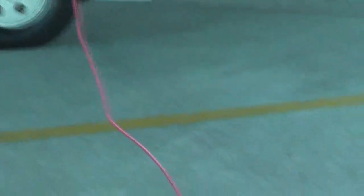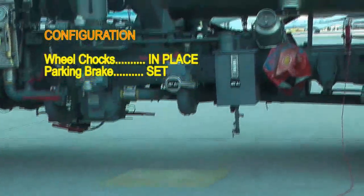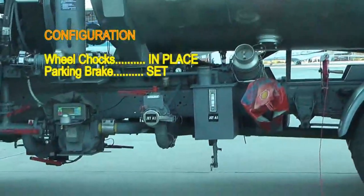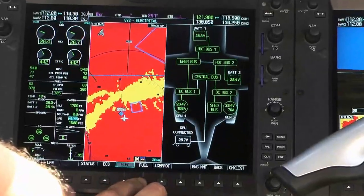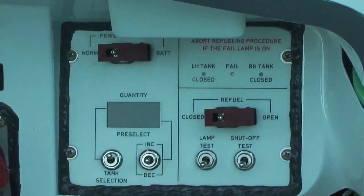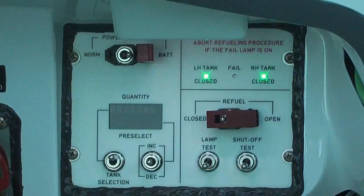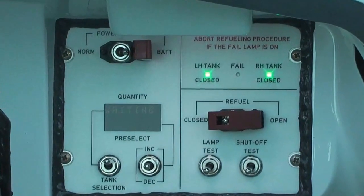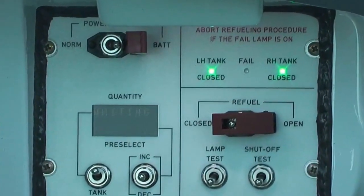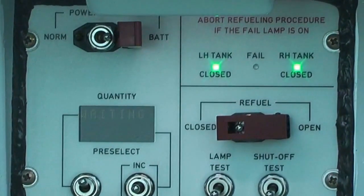Pressure refueling. Make all grounding connections between the fuel source, the airplane, and the fuel nozzle. Energize the airplane with an external DC power supply or set the power selection switch on the refuel control panel to battery position. Make sure the refuel switch is in the closed position and the left-right tank lights are on.